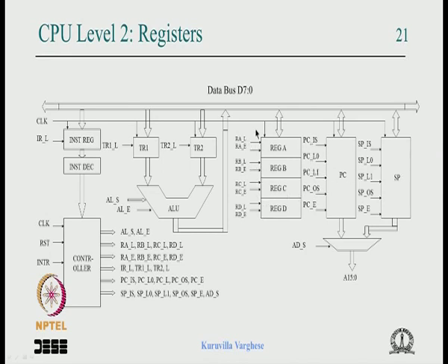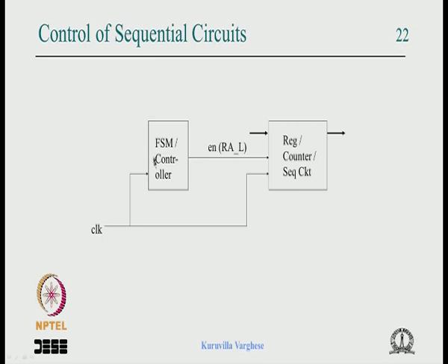So continuously each clock the data gets latched, maybe in a FIFO or a counter which is getting incremented, though it may not make sense for the CPU register. We were looking at how the design should be to make that happen. That means when the latch signal is high and the clock comes, the data gets latched. So that is what is shown here.